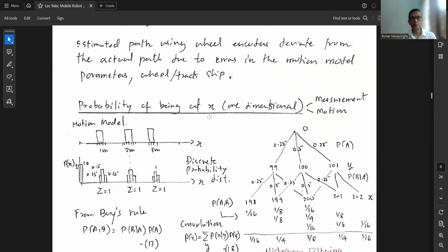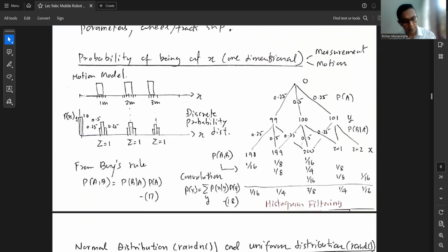All right. Now, today, we are going to discuss a new aspect of robot localization. This is primarily after the work by Sebastian Thrun, and he published a book called Probabilistic Robotics. In that aspect, we consider the position of the robot as a probability distribution, okay? We don't say where the robot is, right? We don't know, but we say there is a higher probability for the robot to be in that particular location. And the robot position should be somewhere around that point.